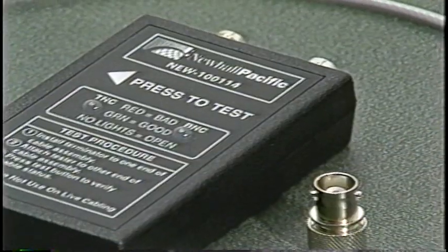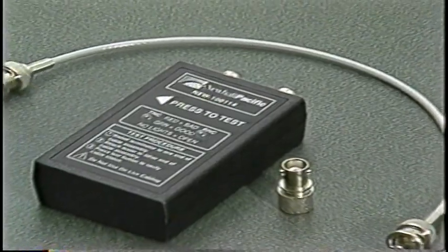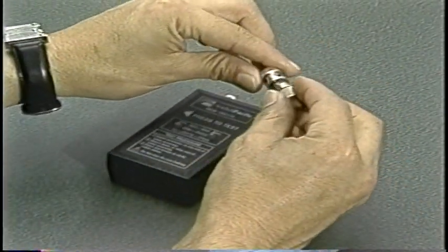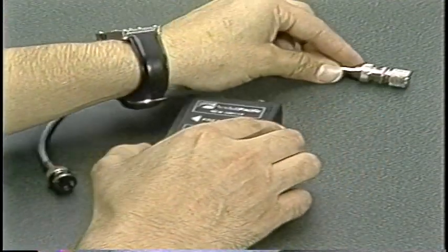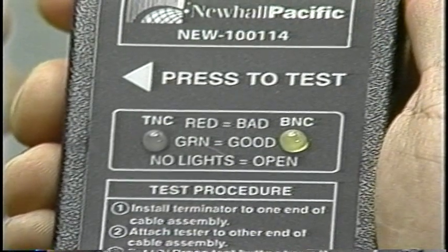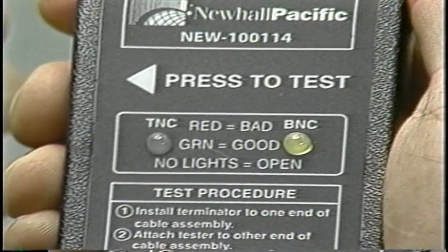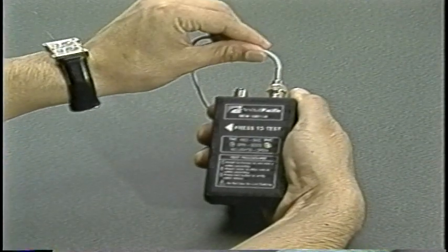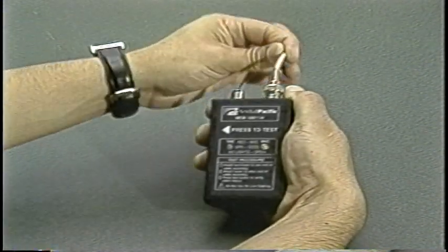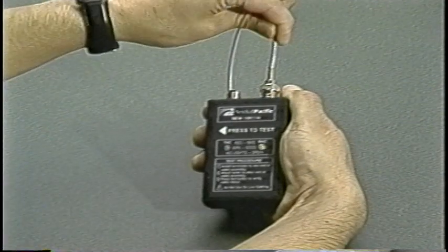The suggested method for doing this is shown here. Apply a continuity tester signal from a test set to the newly installed cable assembly. Provide a loop back on the cable being tested. Connect the continuity tester to the return cable. Now physically flex the cable at all the new connectors, including splices, and check the test set for errors.